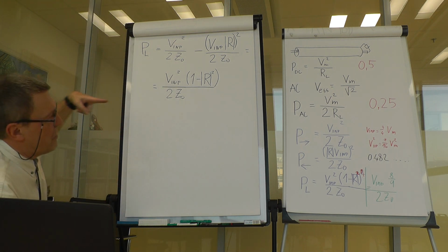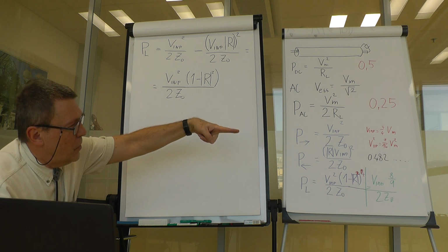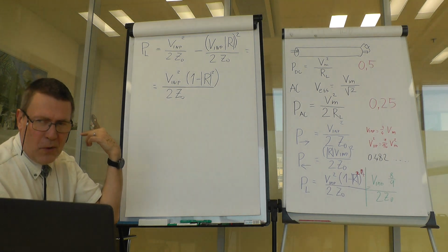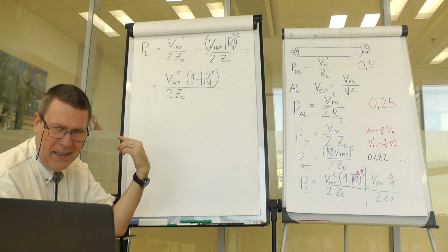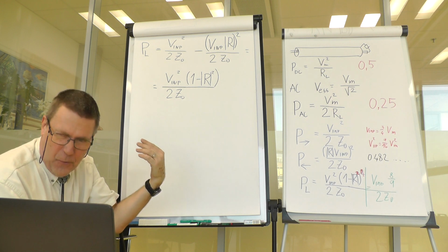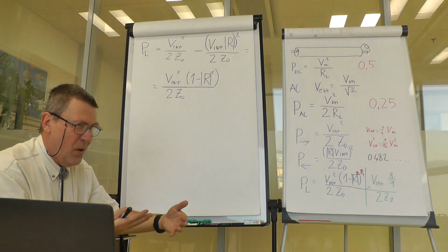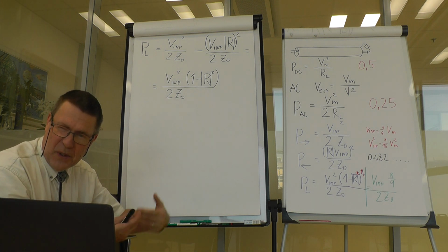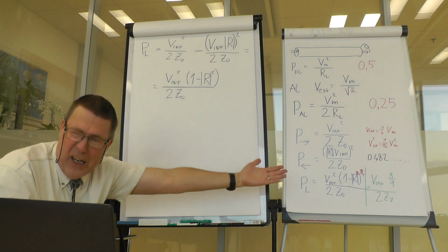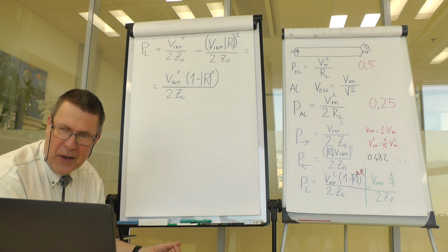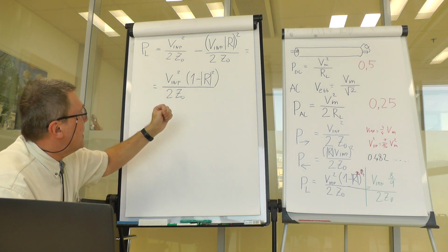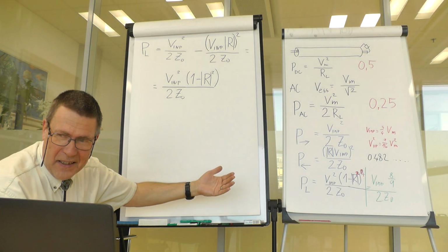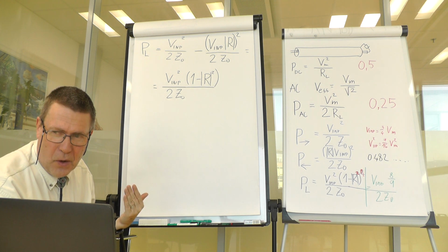There is some power carried from the generator to the load, but some is reflected back. So only that part of the power that does not reflect back remains in the load and therefore causes heat or drives the input circuit of the amplifier, so it gets propagated, amplified to the output or elsewhere. So this is an important point, that what gets reflected is not delivered to the load.